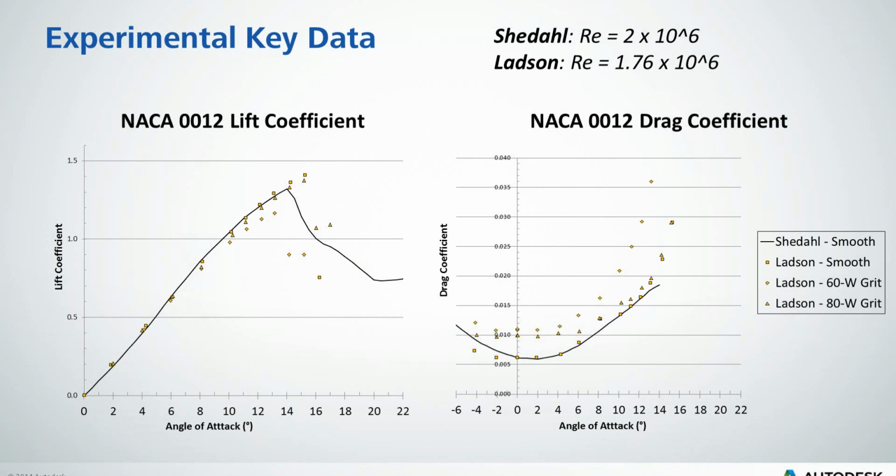The lift, especially at lower angles of attack, agrees very well with or without any sort of leading edge tripped testing. But as we add extra angles of attack, the data starts spreading for the lift, and eventually we get a little extra lift before stall at angles of attack around 15, 16 degrees and so forth. Afterwards, things get a much larger spread, a little more uncertainty.